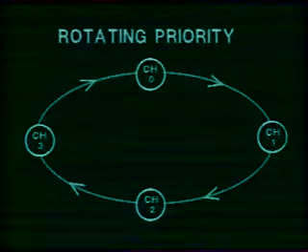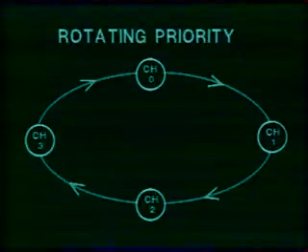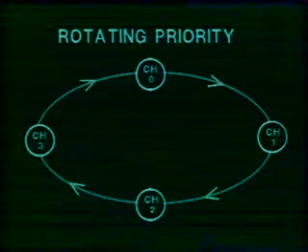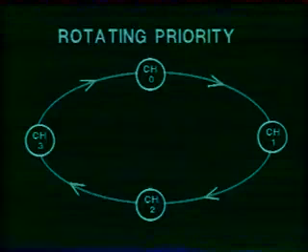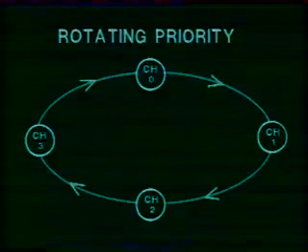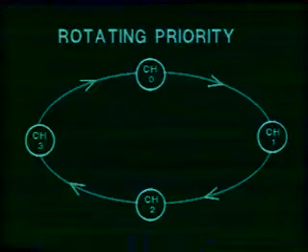For example, suppose channel 0 requested DMA operation and has performed this operation successfully till it was disabled because the terminal count becomes 0. You will find that channel 1 will become the highest priority channel, channel 2 will have the next higher priority, channel 3 will get the third priority, and channel 0 will automatically get the lowest priority.